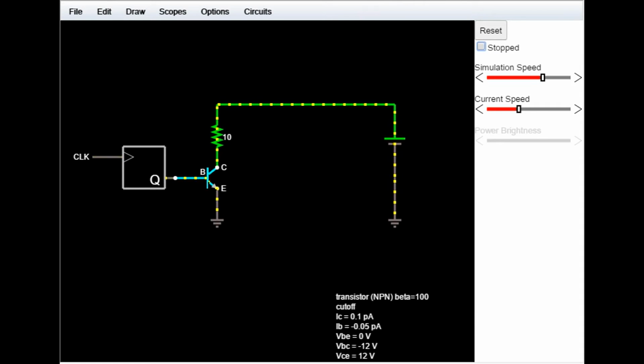Transistors don't have a lot of internal resistance. So what happens is you have your microcontroller driving the BE current, and there's no resistor in this equation. If you look down in the bottom right, you can see that the current going through here is infinite. This is actually a short circuit. It's a very fast way to burn out not just the transistor, but the microcontroller. There are a lot of ways to burn out a microcontroller, and this is one of them.